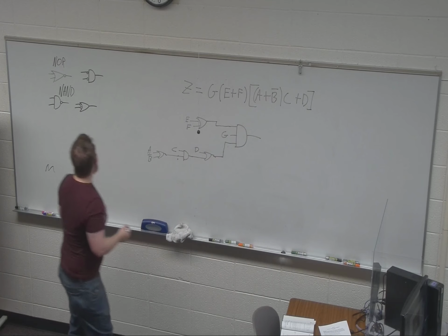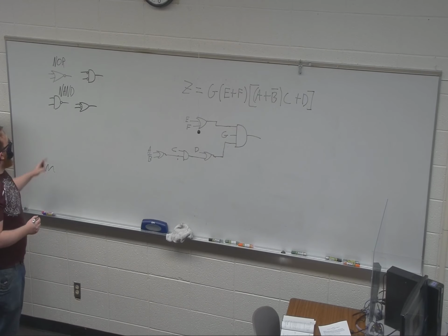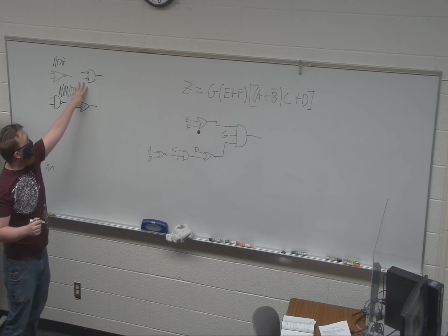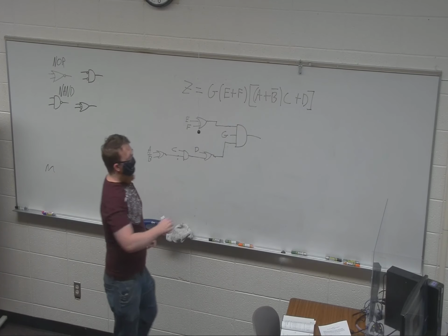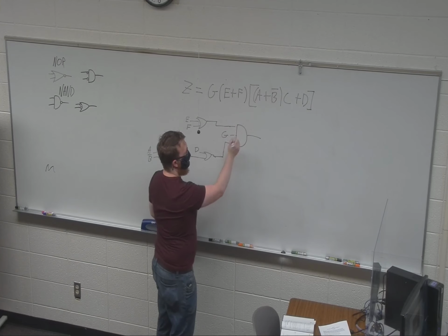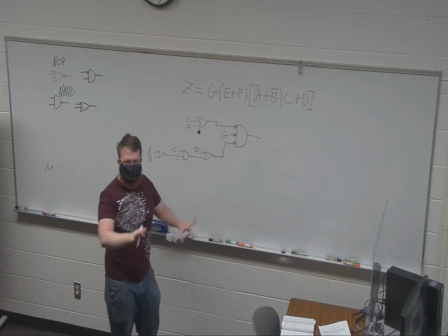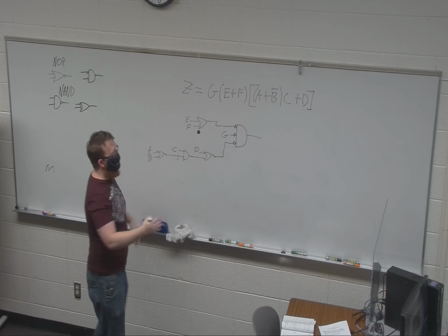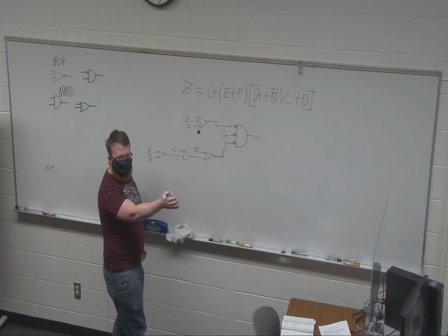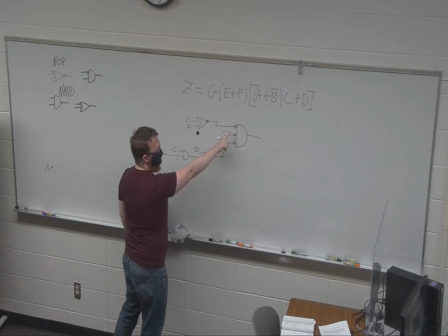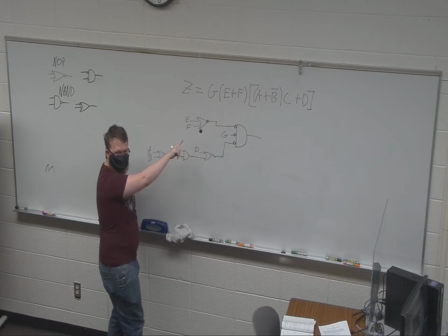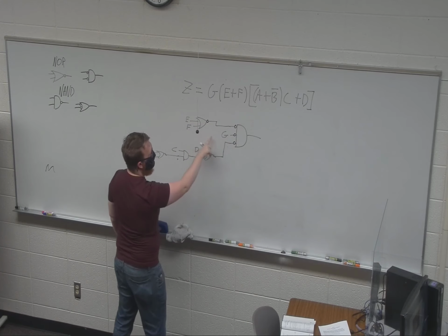And we do so by looking over at this, the NAND or NOR. And this one's pretty close to what we've got already. So what we do is we just throw an invert at each of these. Now to make this equivalent, all you have to do is, if you double invert, everything stays the same, right? Invert, invert. Now we have a NAND and a NOR. Or, sorry, a NOR and a NOR.